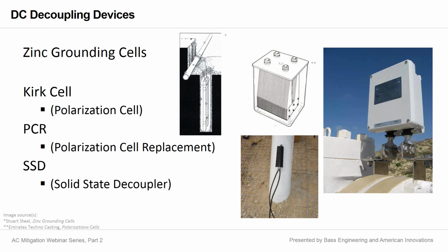Each anode had its own separate lead, and the way that they were designed to be used is you would connect one lead on one side of the insulation, the second lead on the opposite side of the insulation, with the idea that you created a low resistant path between the two anodes. The hope was that there was a high enough resistance that it would block DC, but would certainly pass AC under a high voltage condition.